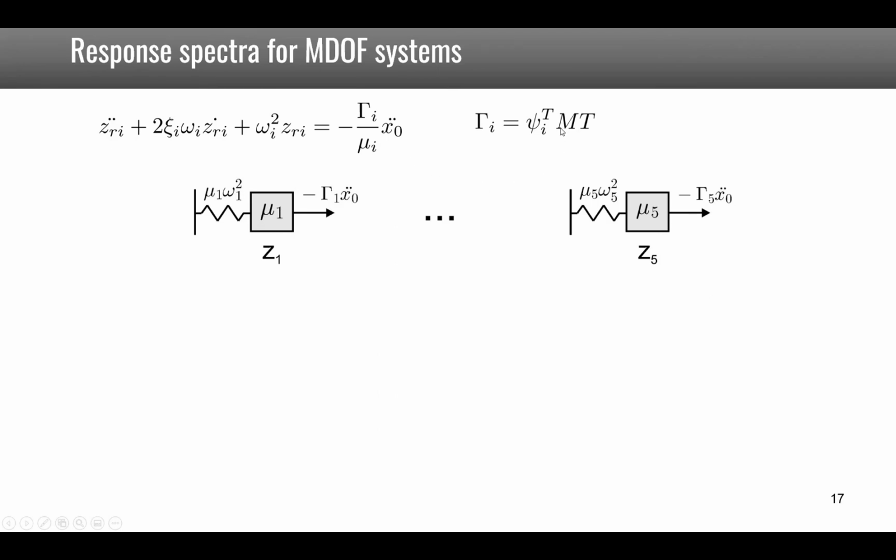This means that if you are looking at the response spectrum, first you can determine the maximum amplitude, in terms of modal displacement, by solving this equation, and then you have to use the amplification factor. The maximum will be given by SU, the relative displacement spectrum, and you just take into account the amplification factor to get Zi max.